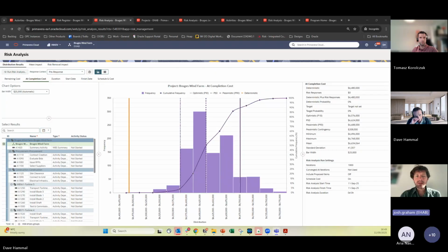But we are doing a piece of research right now because, clearly, at the moment we model things on a daily basis. So if it rains over 10 millimeters of rain in a day, and that's your threshold, then that will be counted as a down day. But what if you have 10 millimeters of rain every day for 5 days? Each of those will be a down day, but would that then mean that you have down days afterwards as well, because your site is now flooded?